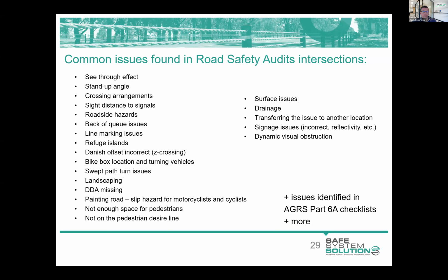either rear ends or vehicles evading queues and spearing off the road into a median or the verge. Yeah, and it's certainly an interesting one at design stage, because you're not only imagining the physical infrastructure built, the intersection built, so maybe there's no intersection there at the moment, or there's configuration changes in the intersection. You've not only got to imagine that, but then imagine it in operation in different times of different queue lengths, and thinking about sight lines to end of queue and all of that sort of stuff. So I think it's a good example of where we need to be a little bit imaginative as auditors in operation. Good. Don't see any particular questions on any of those coming up.